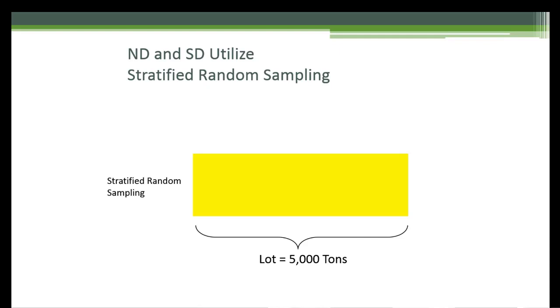One of the reasons why is it's more of a logistical issue, particularly with aggregate sampling and mixture sampling. If your first 4 samples in a 10-mile or 8-mile run day are in the first mile, you essentially overwhelm the field lab and even the sampling system, and that can create errors. Just from a human nature standpoint.